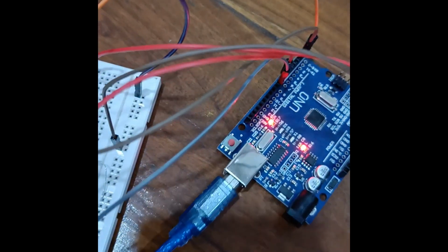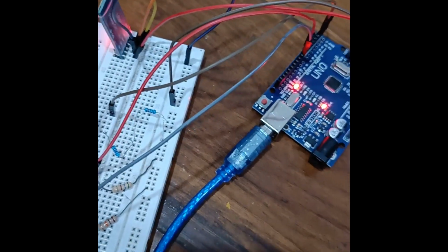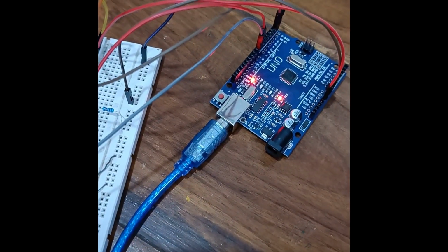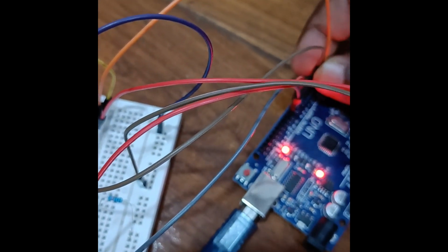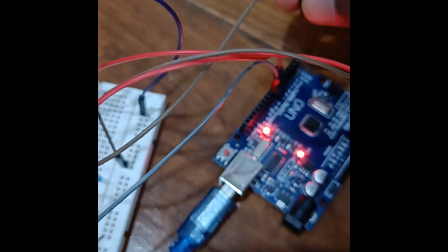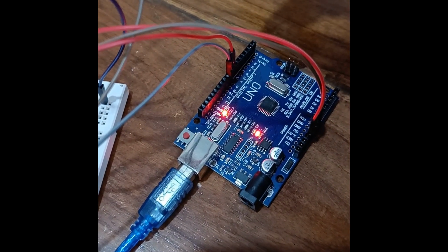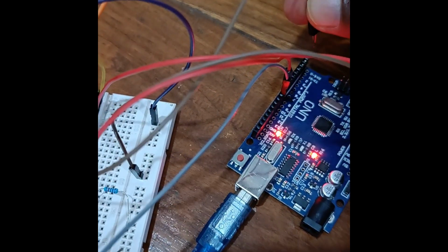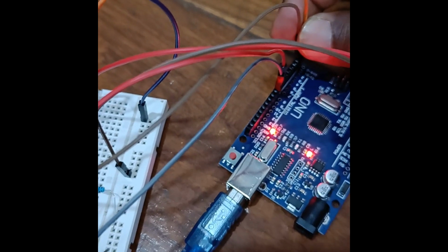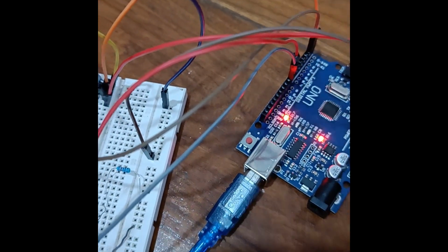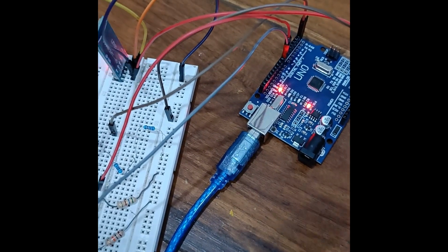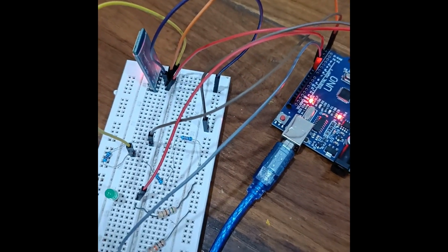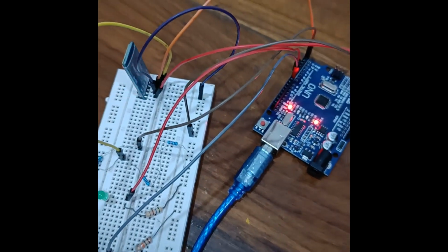But one thing you remember over here, that when you're dumping the code from your laptop to this Arduino board, you will open this connection. I mean to say the receiver and transmitter connection should be opened. Once the code is dumped, then you can connect it once again, because these pins are used for serial communication. So while you dump the code, this pin should be open, and when the code is dumped, then you can connect it, for the code which I have taken.